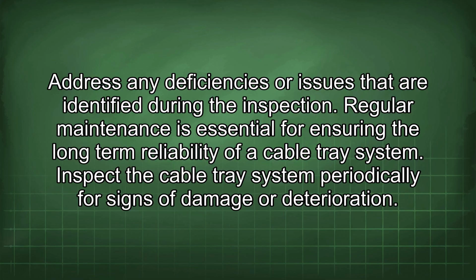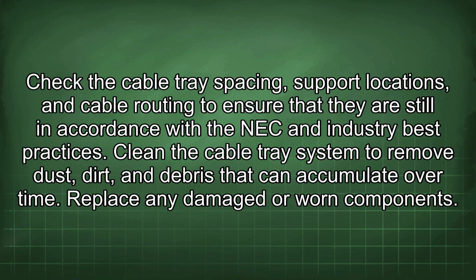Regular maintenance is essential for ensuring the long-term reliability of a cable tray system. Inspect the cable tray system periodically for signs of damage or deterioration. Check the cable tray spacing, support locations, and cable routing to ensure that they are still in accordance with the NEC and industry best practices.